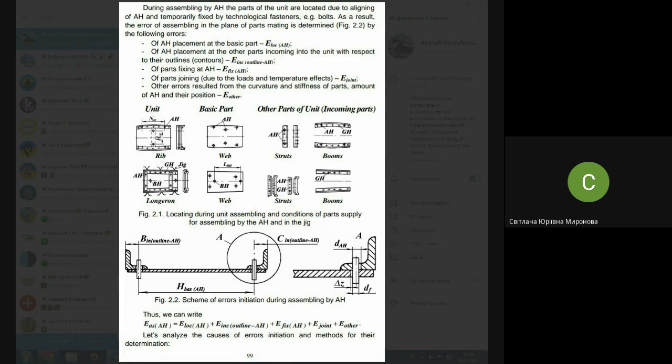In some cases, you have assembly holes and guiding holes, pilot holes, in caps. In another case, you have only guiding holes in caps and no assembly holes. In one case, you have assembly holes in the web. In another case, you have assembly holes in lesser amount. And base holes, or coordinate fixing holes, you may call it like this or like that. In this particular case it doesn't matter, but use the same name each time, either CFH or base hole. It is up to you, but the same name permanently.